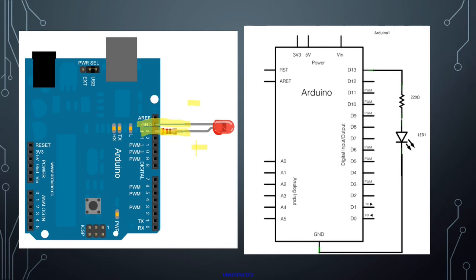So this one we're connecting to pin 3, and so in our program when we note pin 3, that's what's going to control this LED. We could just as easily plug this resistor down here into pin 8, and we could control this with pin 8. And so any of these is acceptable. You can kind of connect it anywhere.